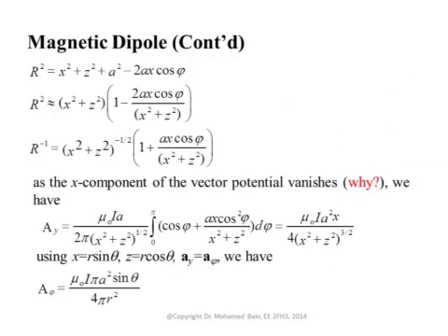So if you assemble all these terms together, this is now r squared. I remove the square root. This is r squared. We can take x squared plus z squared as a common term, and now neglect a squared over x squared plus z squared, because we assume that we are calculating the field far from the wire and the loop is small. Then a is way smaller than x squared plus z squared. Remember, x and z are the coordinates of the observation point, which is assumed to be far from that small loop. Then a squared over x squared plus z squared is neglected.